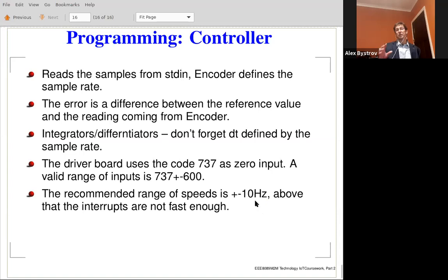But as the system potentially may overregulate, it will go from 0 to 2 Hertz, but as a transition, a peak may happen, which is 5 Hertz, or 10 Hertz, or 20 Hertz. If it is 5, it's fine. 10 is fine. If it is 20, then expect abnormal behavior. It may register 20 Hertz as if it was some other number, which is not good. You will see that this results in a significant error in operation. The system may just start accelerating because it will decide that the speed is insufficient, although it is exceedingly high.